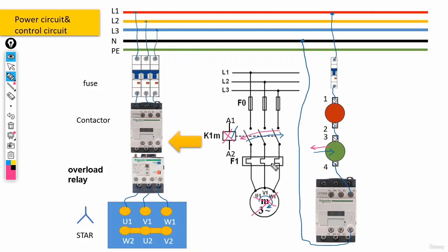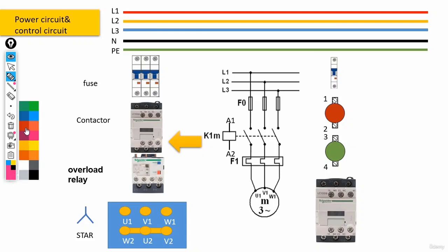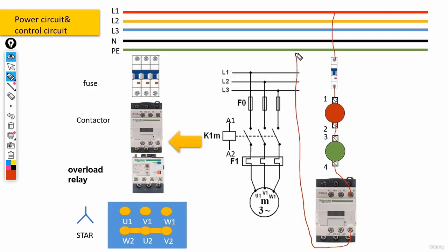Now, guys, let's say we have successfully started the motor. We have turned the motor on. The question is how we can keep it that way. In other words, how exactly we can keep the motor running. Okay, let's see how. Well, if you remember, we had a couple of terminals here called 13 and 14. We need to connect these to our start push button. Let me just draw the sketches that I had before.